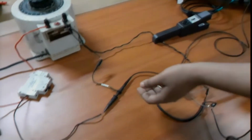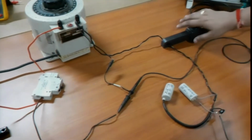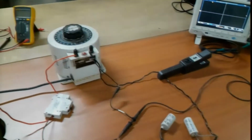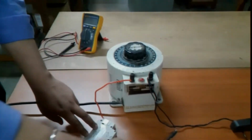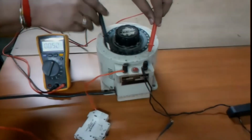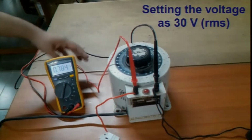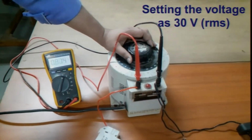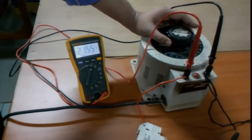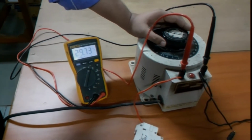So, we will give a step input. In fact, to avoid nonlinearity in the inductor, we will not give a very large voltage. What we will do is we will actually apply a small voltage. We are using 30 volts RMS in this experiment.